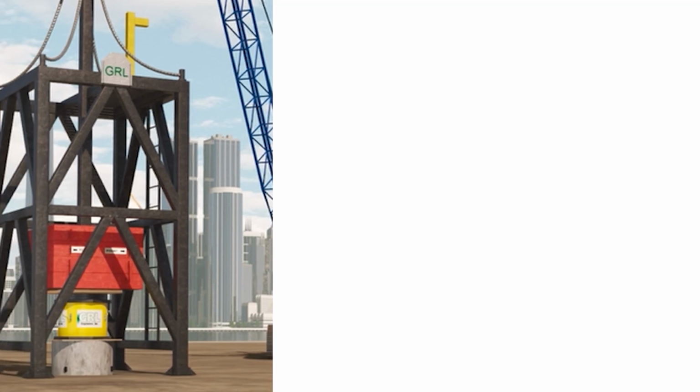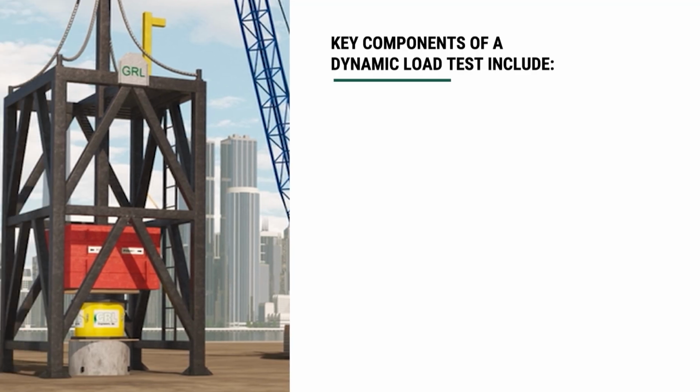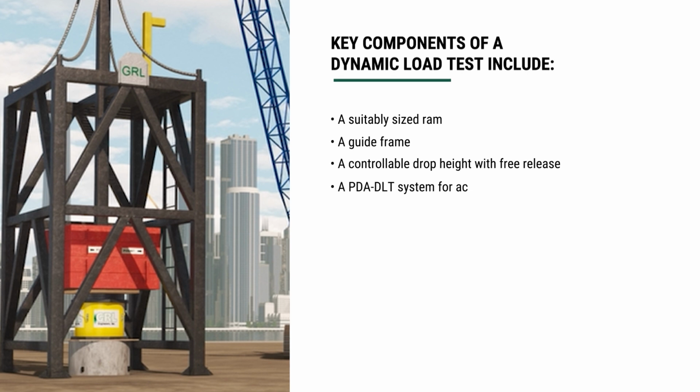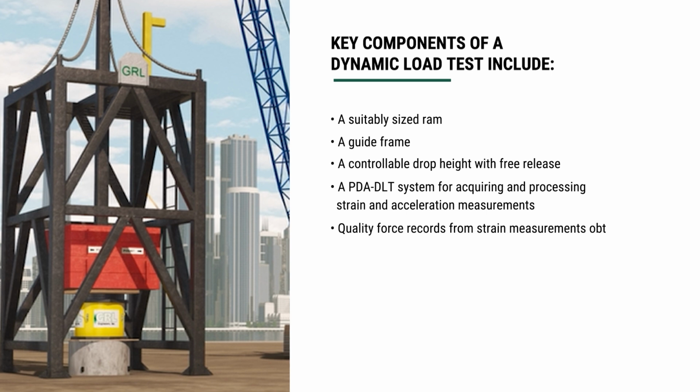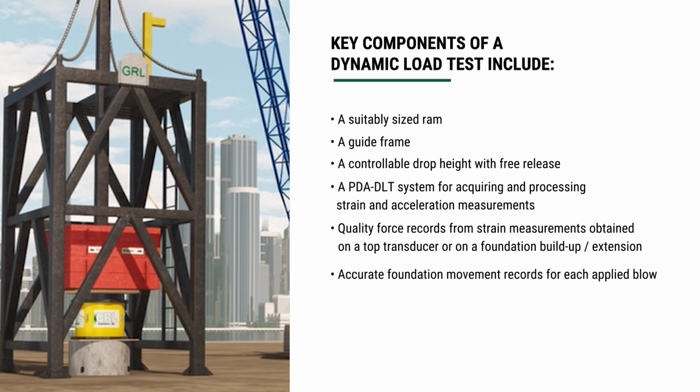Key components of a dynamic load test include a suitably sized ram, a guide frame, a controllable drop height with free release, a PDA DLT system for acquiring and processing strain and acceleration measurements, quality force and velocity records, accurate foundation movement records, and CapWAP software and experienced analysis personnel.